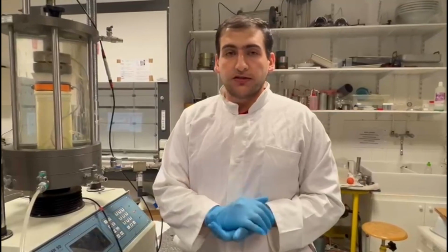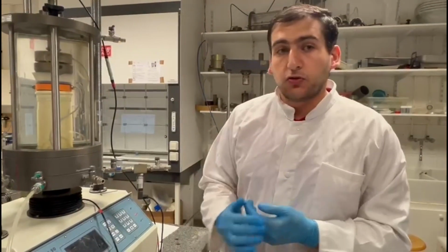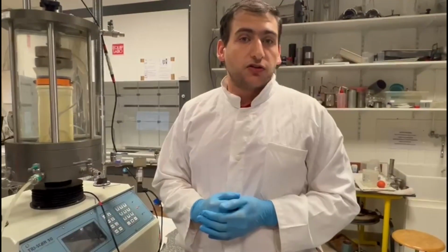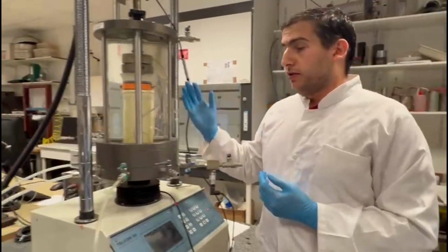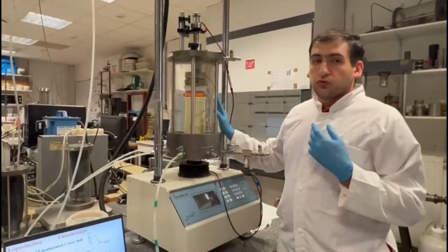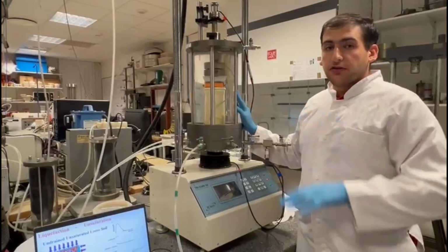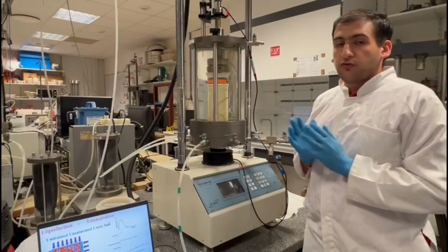What is the limit of unsaturation that should be in the soil? At what limit should the air be in volume with respect to the water so that we will not have the liquefaction phenomenon? To do this, we base our research on the triaxial apparatus that we will use to duplicate the same phenomenon that occurs inside the soil at different depths, so different consolidation, confining pressure.